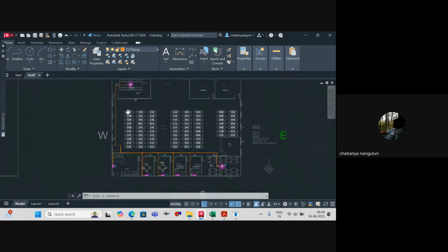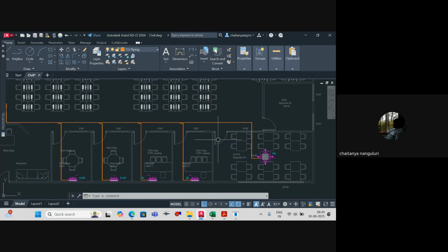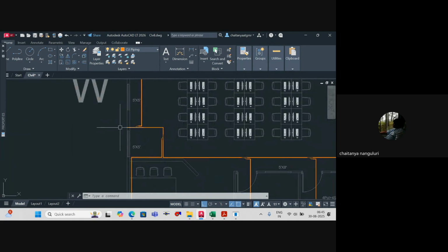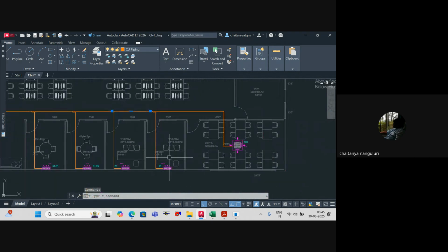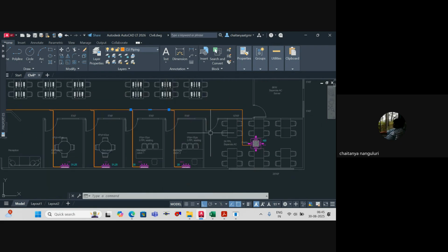Now what we have to do is add the capacity indexes to get the pipe size. Understood? So here, this one is 100, this is 20. So this automatically becomes 120. Now what is the pipe direction? The pipe is coming from here. Don't you think this pipe is supplying refrigerant to these two equipment? So even though I've drawn one line, it basically means two lines. One is suction and one is liquid line, not discharge. Discharge will be inside the outdoor unit. So you have your suction line as well as your liquid line.